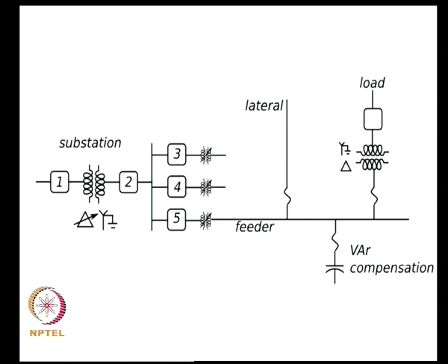Okay. You also have devices such as reclosers and sectionalizers. Reclosers are essentially, you can think of it as a breaker which has the ability to actually close again after opening. The reason why people would like to use reclosers is that most faults are actually temporary, and so once the fault is cleared, you can actually re-energize the line. So, people consider using reclosers rather than some line maintenance person later on coming and manually turning on the line.